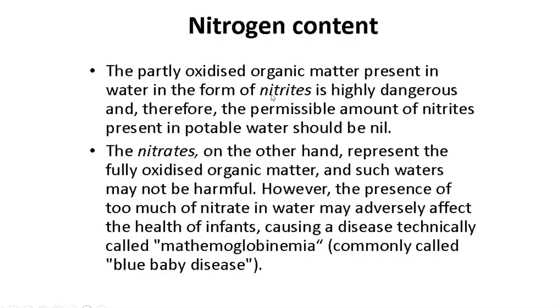The partly oxidized organic matter present in water in the form of nitrites is highly dangerous, and therefore the permissible amount of nitrites present in potable water should be nil. Even a very minor concentration of nitrites in drinking water is dangerous for humans as well as other water bodies, such as fish and other marine life.